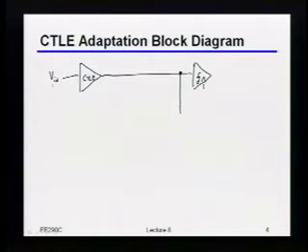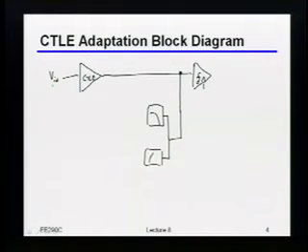Can I just put a filter? Yeah. Do I need one filter? Two filters, right? So I basically do one low-pass filter and one high-pass filter. If I've done this right, then the cutoff frequencies of both of those filters should be the same. There should just be some half-point frequency. Now once I've done that, how do I decide which one has more energy? Or how do I compare the energies?